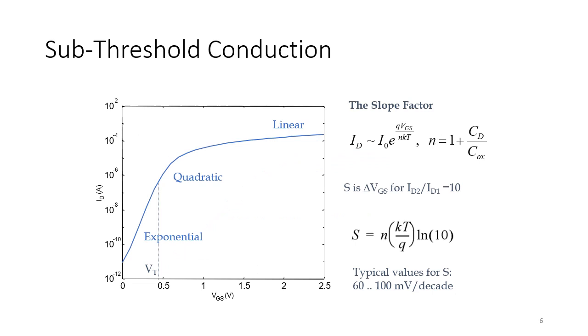Subthreshold conduction: when the device turns on below the threshold voltage, that conduction is called subthreshold conduction. In that case, the device turns on even when the gate voltage is less than the threshold voltage. This may occur due to shorter channel lengths.